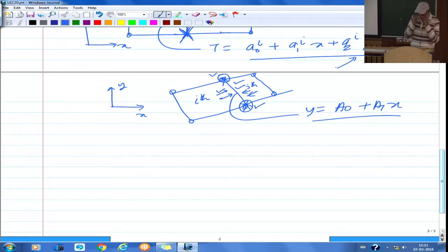So, then one more question was about the reduced integration, which I had talked about before the mid semester break. For the Timoshenko beam element, if you have linear interpolation for both, say, transverse displacement and theta z, and as I said, if it is used for solving thin problems, there is shear locking, it actually underestimates the deflection.